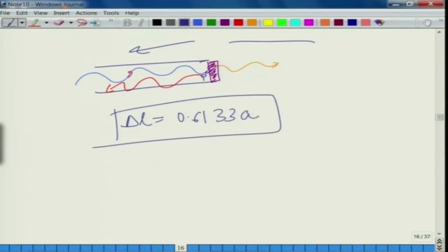So, you can have situations in which one end is open and the other end is flanged. Then the end correction will be this one plus 0.85 times A, whatever it is. So, we can consider the corresponding cases as well. It depends on the application of the end correction, so we must carefully choose that. I will present to you one example before I close this particular discussion.